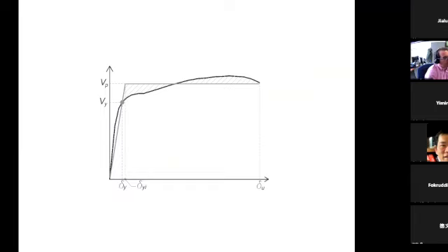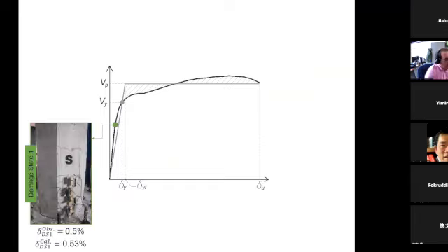There was a column that we tested here at our lab, and that was not included in the database that I discussed earlier. So that would have been a good calibration and validation of the equation. Our equation says at 0.5% drift ratio, again, drift is lateral displacement of column normalized to length of column, at 0.53%, you should see damage state 1. And in fact, in testing, we saw the same thing at 0.5% drift ratio.